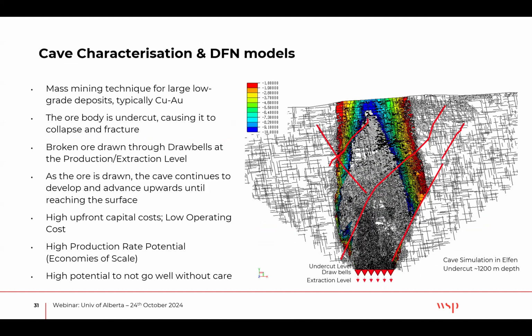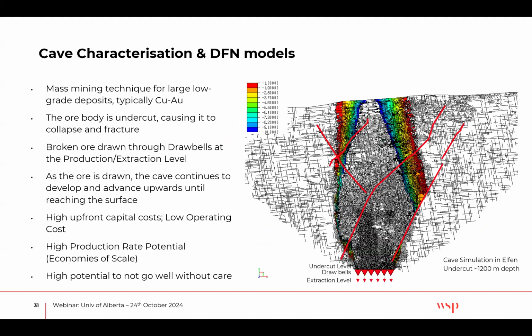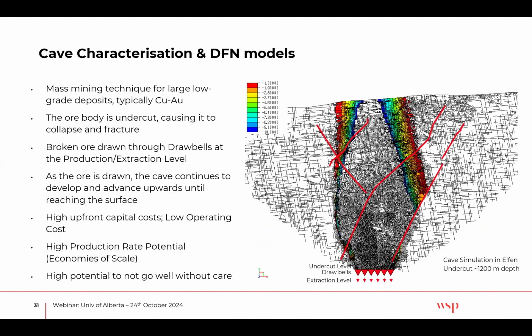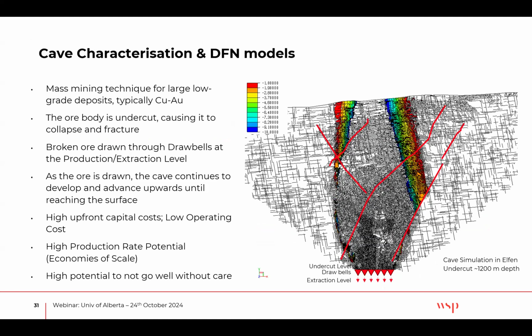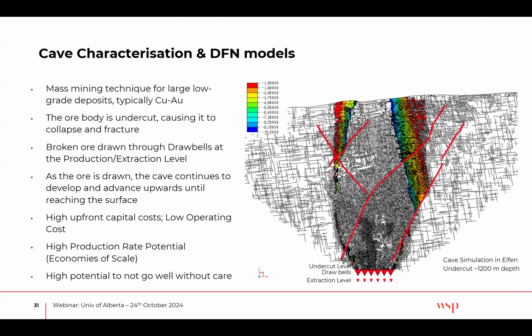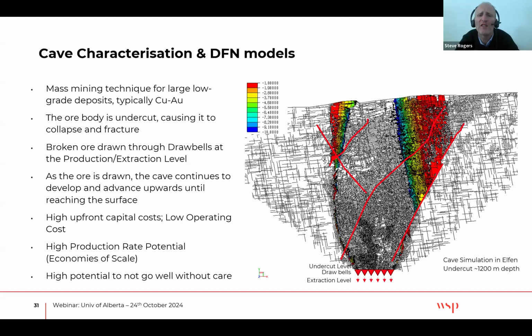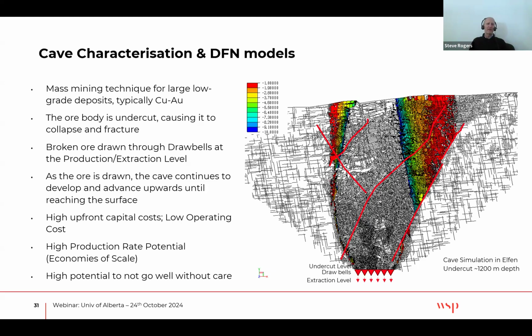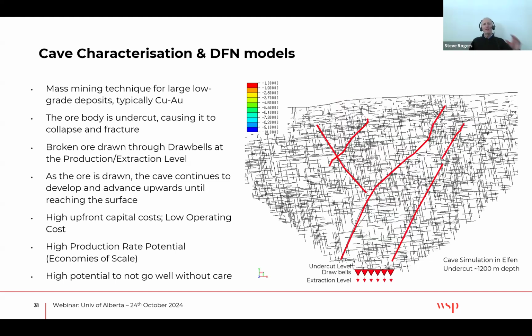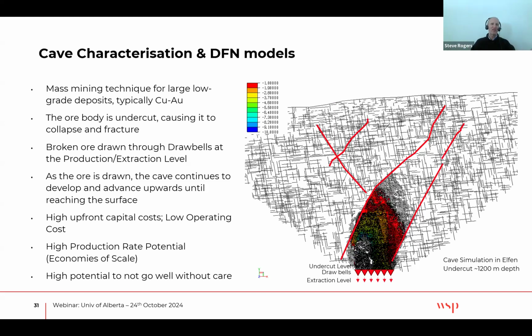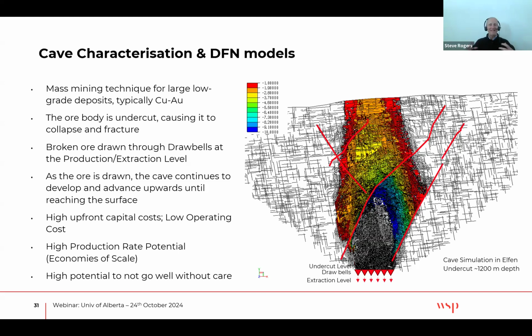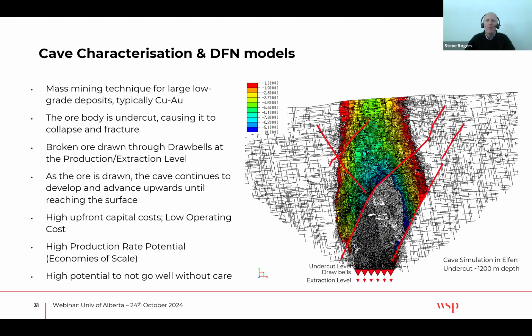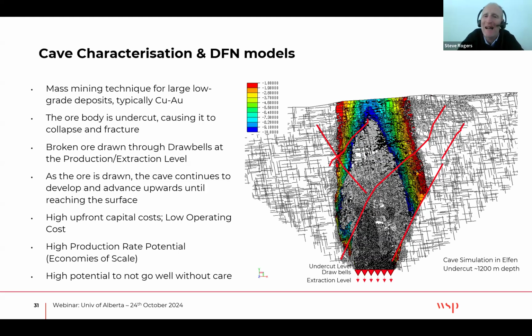And you could see you have installed DFN already in the model, but when you are doing the caving, we could clearly see there are a lot of small fractures that have been developed inside of the cave, right? Yes. This software is ELFEN, which is a finite discrete element model. So there are blocks, and the blocks themselves can break. So again, it's a hybrid failure mechanism. Part of the failure is associated with the DFN, the existing structures in the system, and then obviously the intact rock does break as well. But really we should think of this model as a rock mass model.